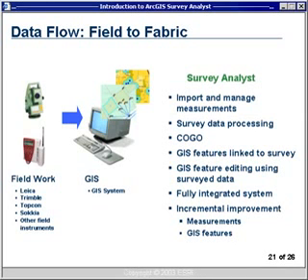I can conduct a traverse, for instance, a total station computation. So I can do the standard survey computations on the raw data and create survey points. I can also, for instance, conduct least squares adjustments by adding new data and recomputing. So Survey Analyst supports that data processing.